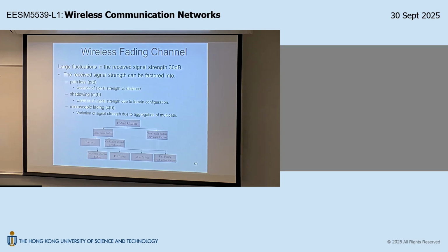In the link budget analysis, of course, you need to consider range, right? Range is the distance separation. How far can I separate from the transmitter and still receive the signal? That's called range. Therefore, that requires a path loss model. You need to understand in your particular environment how the distance affects the receive power. This is called the path loss model. You also need a shadowing model, right? In your environment, what will the shadowing process be like? Because these two things will affect your link budget.